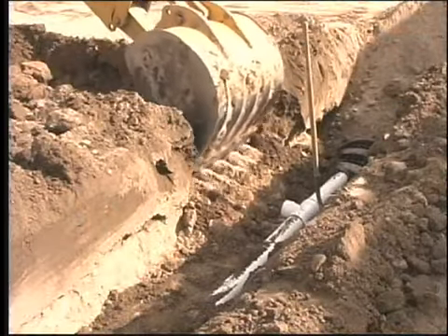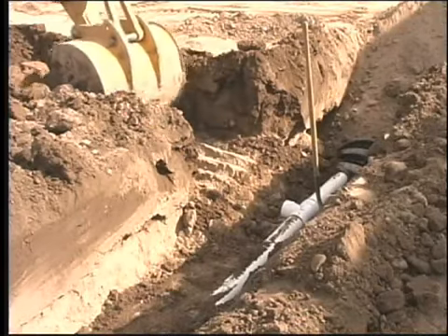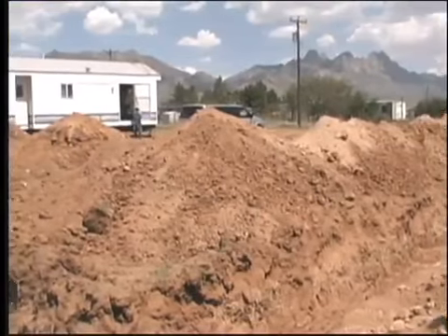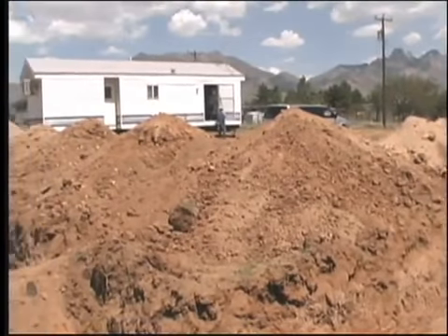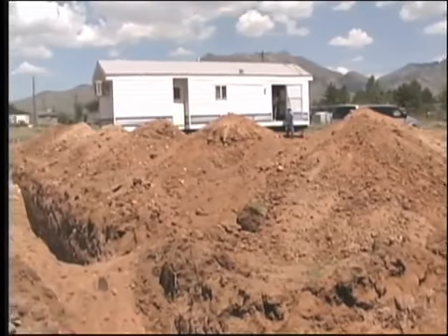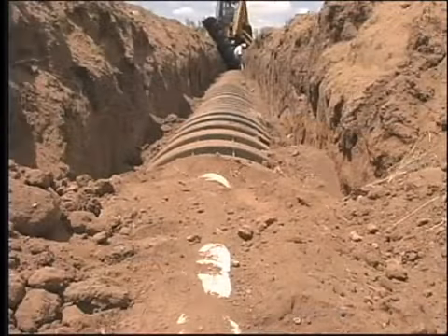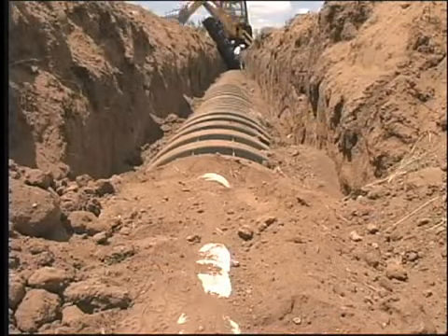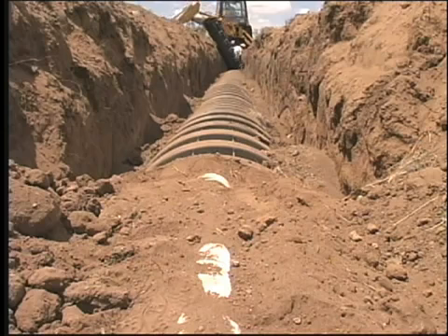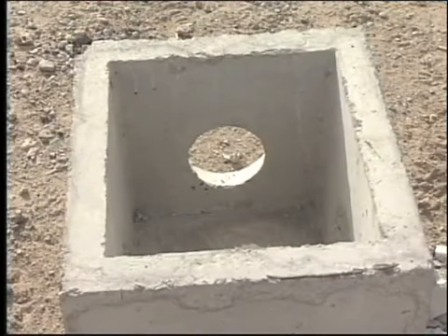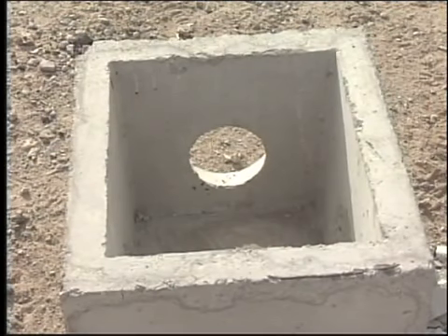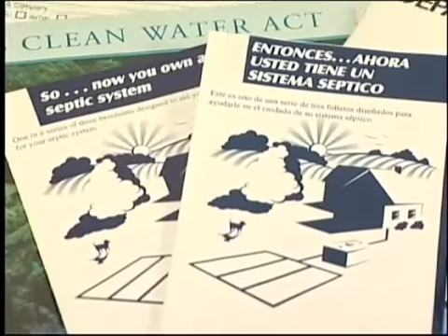For both level and sloping sites, trenches should be connected by a header or manifold trench. The far ends of the trenches may be connected on the level sites to further improve wastewater application. If you have only 1 or 2 trenches, many regulations require no distribution box. However, if you have more than 2 trenches, a distribution box may be required.